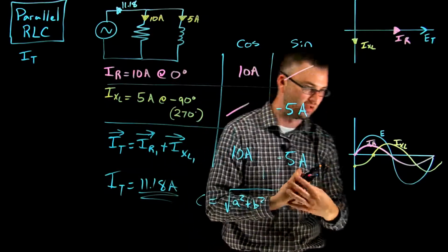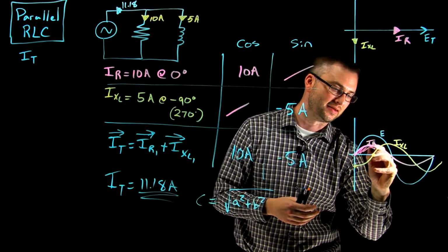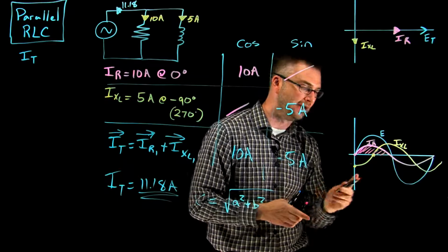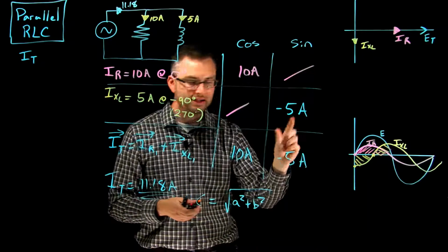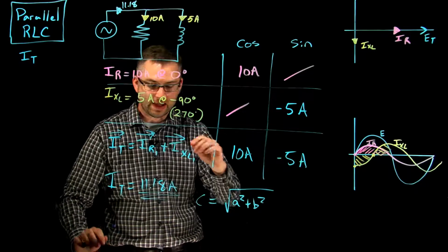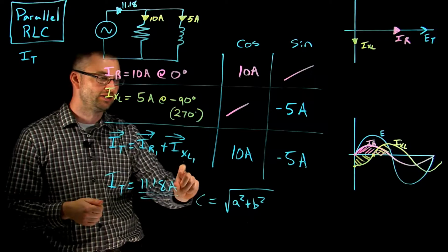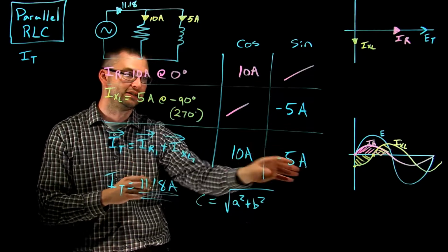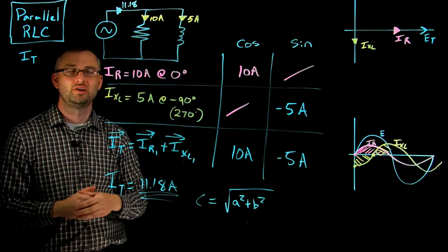And why is that? Well, we just got to remember, the currents aren't flowing at the same time, so we're taking this current in here, and we're adding it to this current in here. So we just want to kind of take that into respect that we're adding currents that are happening at different times, and there's some overlap in there, and that's the total, and they're fortunately at 90-degree relationships. So it's very simple to solve for total current in an RL circuit.